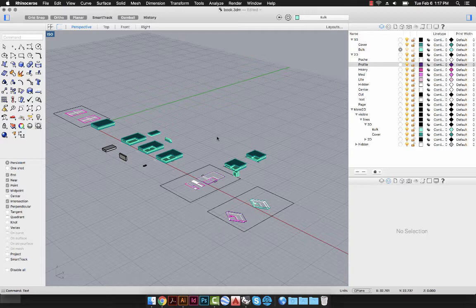2D. And that will be the next thing I want to show you guys is how to make 2D, the importance of layer organization. So we'll go ahead and come up with a layer system in order to assign line weights more easily in Illustrator. And I will show you how to create a custom grid and then how to export selected. So we'll export our 2D line work to Illustrator. And finally, we will work in Illustrator briefly to assign line weights.